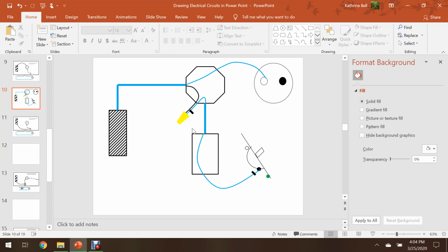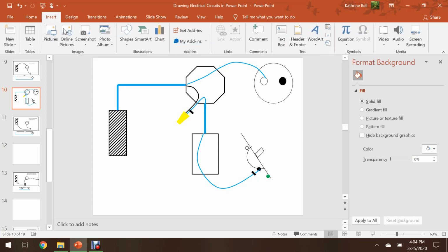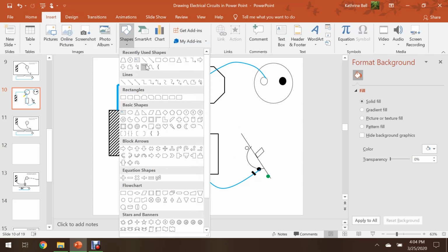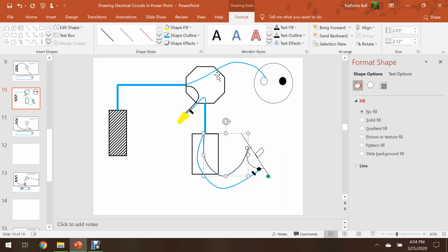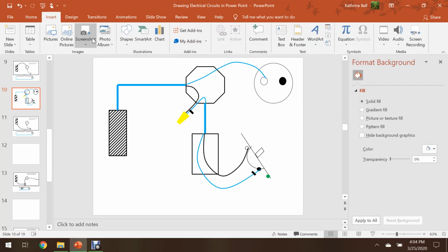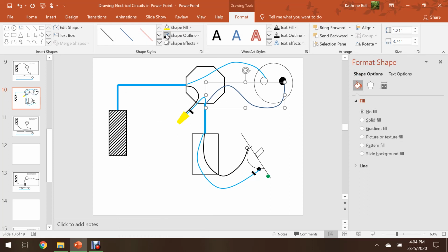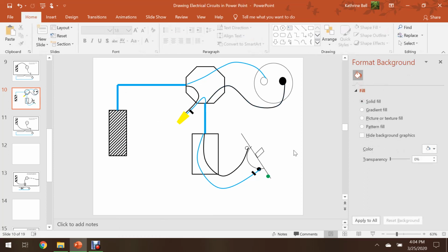All we have to do now is leave the switch and go to the light. And we have a black insulated conductor in our non-metallic cable that we can do that with. So our black conductor is going to come down and connect to the other terminal. I'm going to change that to black. Then selecting the curve again. We have successfully wired a keyless lamp and a single pole switch.